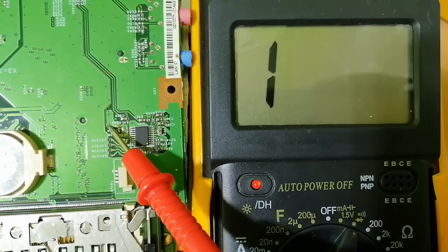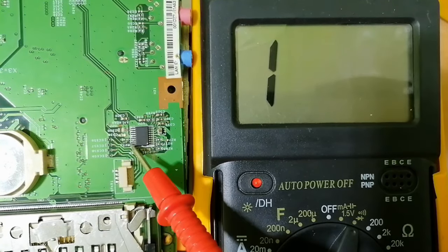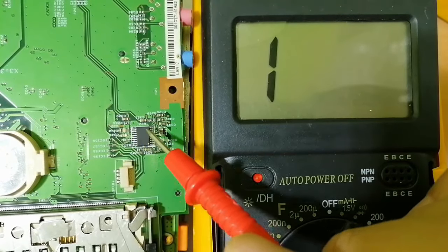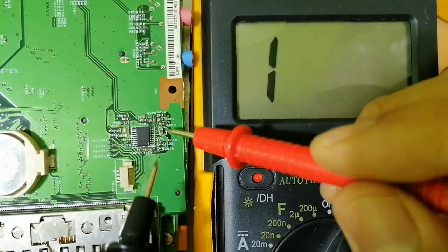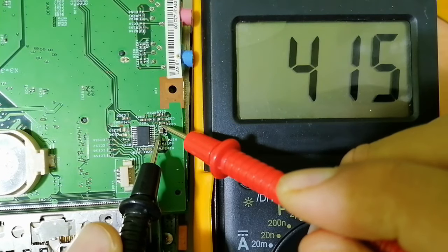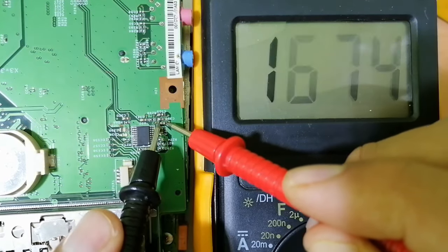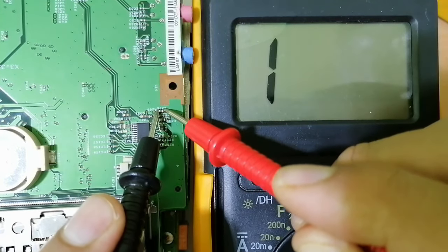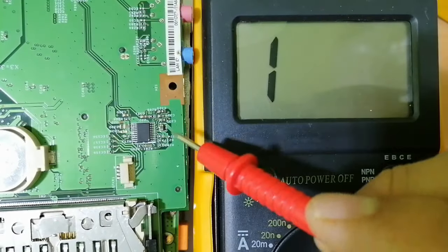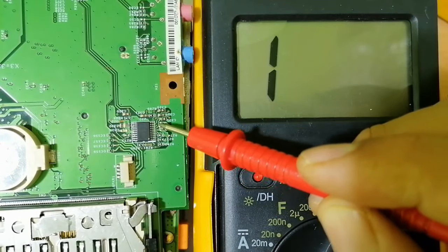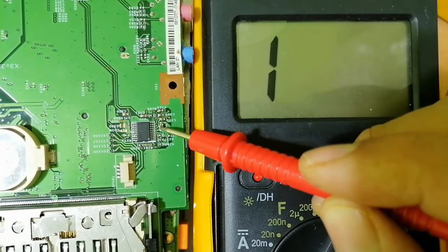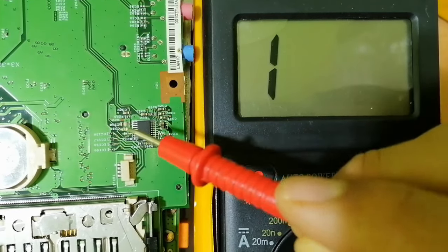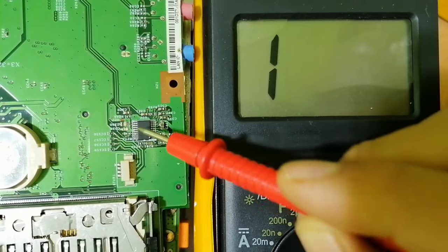Because we have this bolded path here, which means this is the ground. So when you want to check whether the IC is shorted or not, you can just check the ceramic capacitors. As you can see, this one is good, this one also is good, this one also, and this one also. If you find any ceramic capacitor shorted on both sides, it means the ceramic capacitor is not the shorted component; the IC is the shorted component.